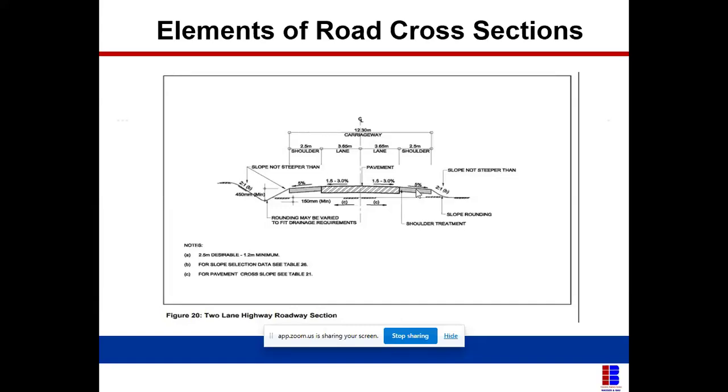So what it means is that if my carriageway itself is having 2.5% and the water is going out on the road, at that shoulder point the camber is normally steeper, so the water will move faster on the shoulder, because most times our shoulders are normally surface dressed. So water will move faster from the shoulder and go to the drain. Sometimes we use edge drain as well. Surface dress on our shoulders. Most times, especially when the project has a lot of money, they pave completely and do wearing and binder on the shoulder, but most times they use surface dressing on the edge of our shoulders.